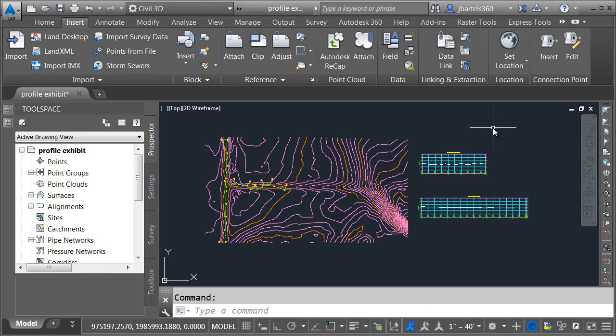So in the big scheme of things, repairing data shortcuts isn't something you'll need to do very often. That being said, you never know when someone on the project team may copy, rename, or erase something they shouldn't have. Using some good file maintenance techniques, along with the data shortcut editor, you should be able to repair or restore just about any data reference.